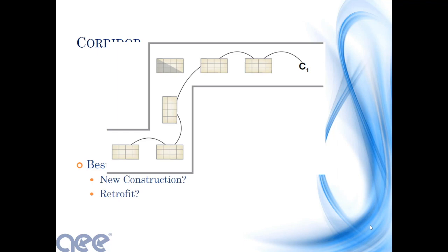So now I'm looking at a corridor. For new codes for corridors, maybe you have unoccupied to off. Maybe you have unoccupied to a low level so that you meet your minimum foot candles. You may have occupied to 70% light level during the day, and 40% light level at night after hours, enough light for security to go around, but not as high a level. So digital would work great, right? Digital would accomplish that. Is that the best way to go?